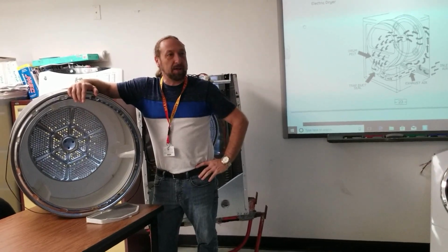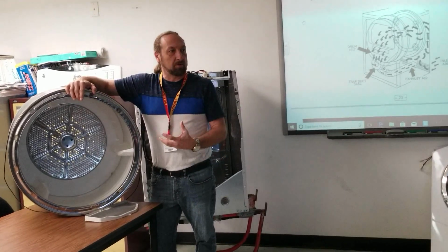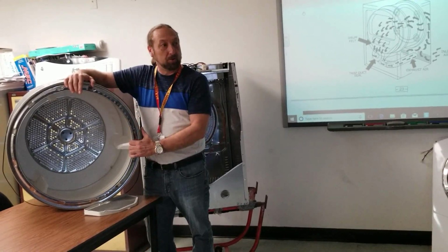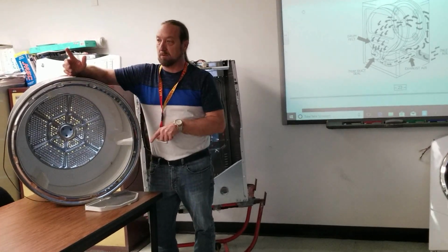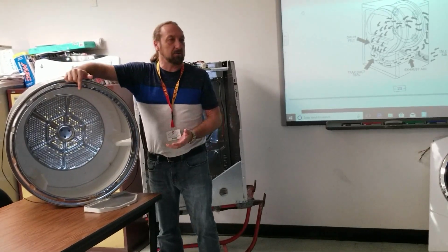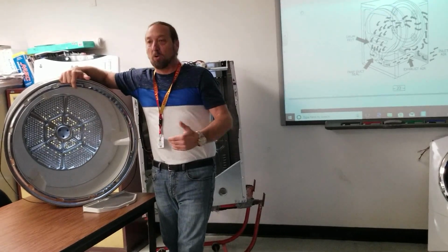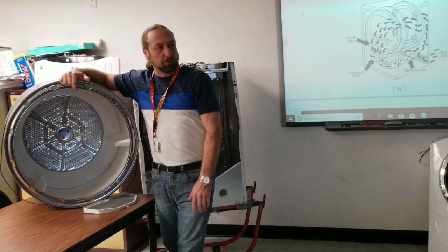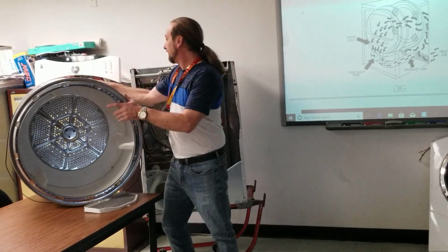And you can identify that when you look at the heater housing or the drums, they'll look burnt. The metal discolors. And when you see that, either you have an airflow problem in the machine, or the hose in the back is blocked, not allowing that air to flow. And if we have airflow problems, we have drying problems. So when you go to someone's house, it's not always something broken in the machine that's going to stop the machine from working. The airflow could stop the air from flowing over the drum, over the clothes, over the heating element, etc.